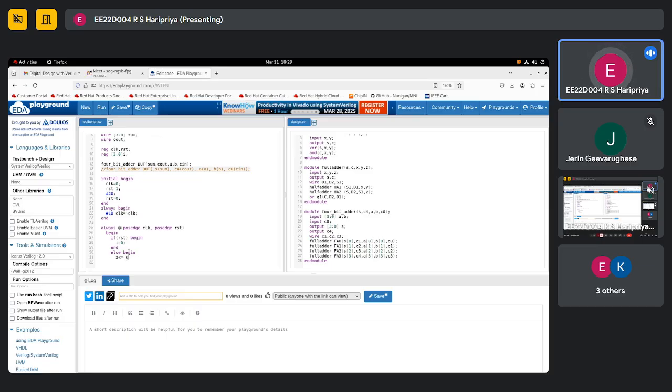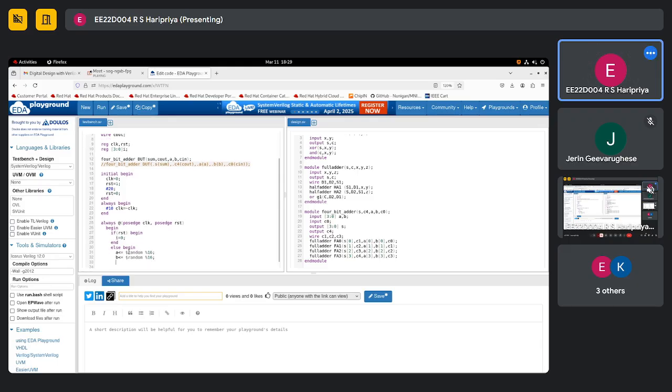This is a random number generator. The system task is $random, and percentage 16. To take a remainder of a number by 16, we can give the output 0 to 15 because we have 4 bits, so the range is 0 to 15. And similarly, B $random modulo 16, and carry CIN is a 1-bit number, so you want between 0 and 1, so percentage remainder of 2.